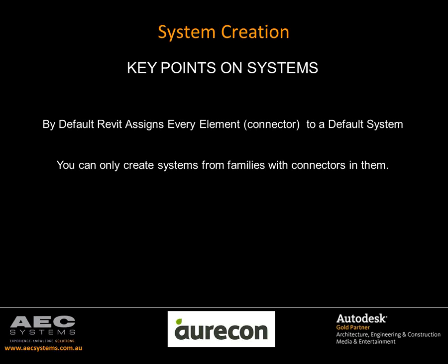So the process of creating systems should actually be reassigning elements to the correct system instead of creating from scratch. Little food for thought there. You can only create a system for families with connectors in them, so you may need to update some of your electrical families to have the proper connectors assigned to them.